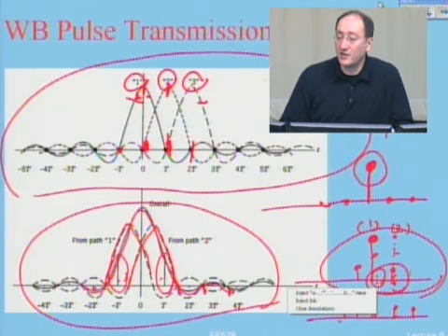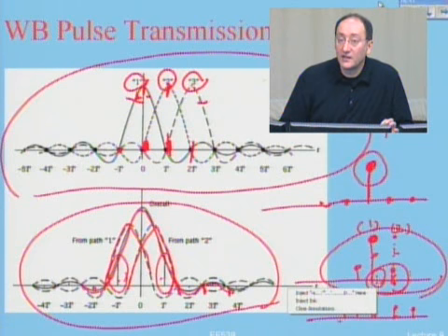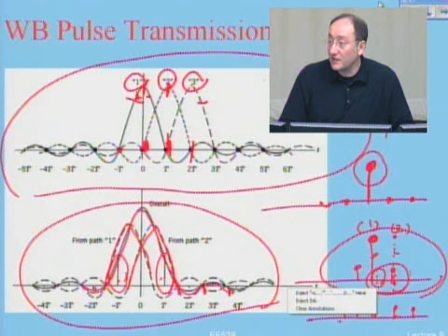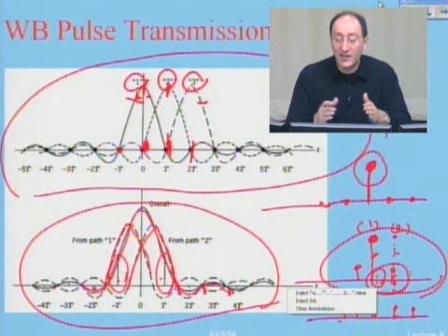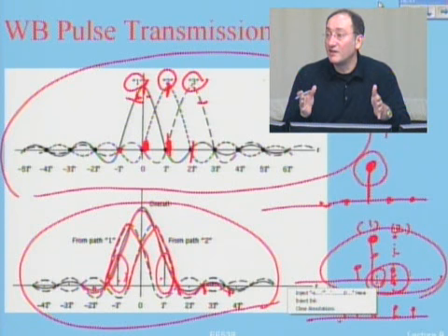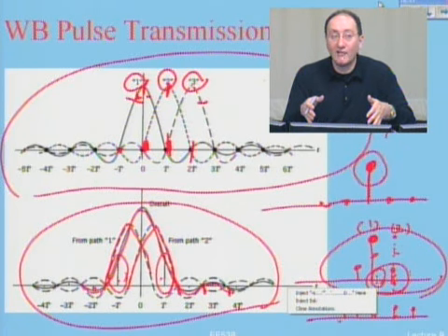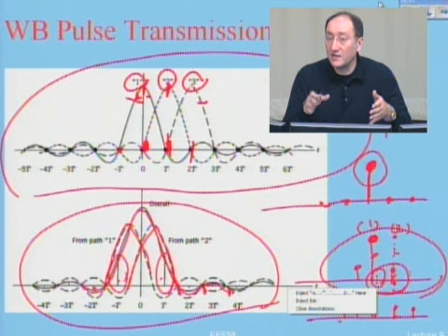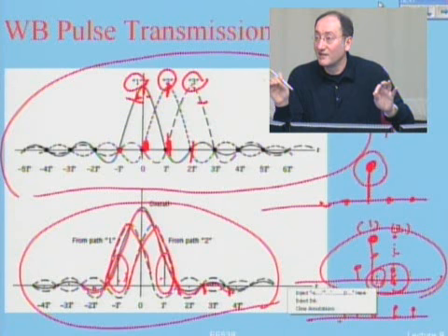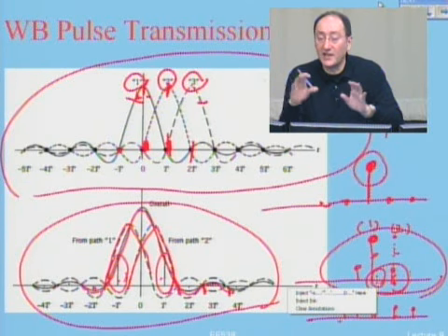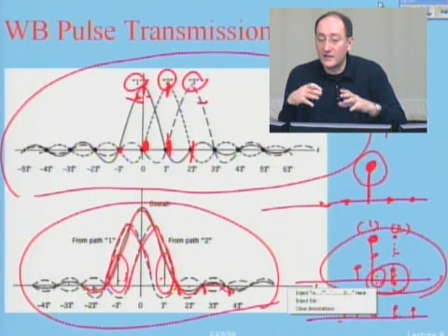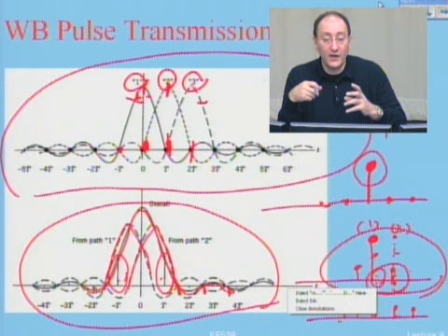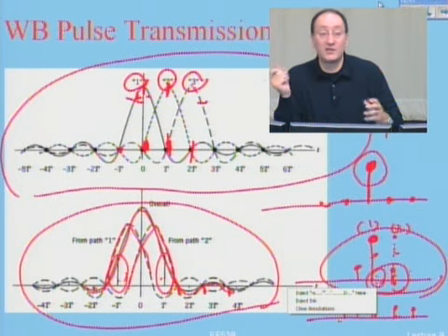So in wideband communication, I have in-band diversity. This is what I call in-band diversity. It means within the bandwidth, I still have a raised cosine with the same bandwidth, but inside that bandwidth, I have more than one diversity. I have a diversified signal. Where is that diversity? Inside my impulse response. If I'm intelligent, I take advantage of that, or I create a situation in which I can take advantage of it. If I'm not, those cause intersymbol interference.